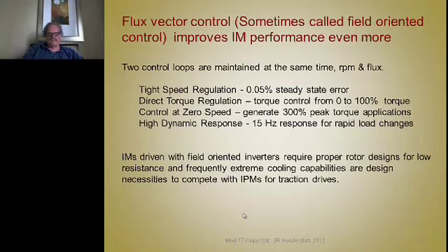But to take great advantage of these kinds of drives, particularly the field-oriented control, the rotor is best optimized for low resistance and to have thin enough laminations, properly insulated against eddy currents, to use for flux vector control, and the right balance between the cross section area for the copper and the iron, so that you can apply maximum magnetizing current and run the saturation in the resulting steel portions of the rotor right up close to saturation.